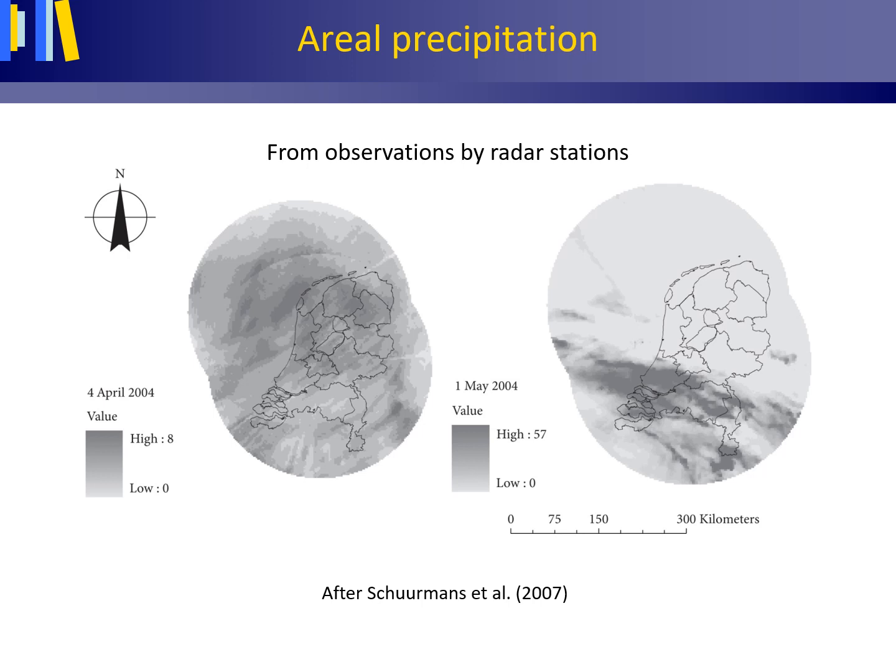Nowadays, good use is made of radar in estimating aerial precipitation depths. Radar does not directly measure precipitation. Radar is an acronym for radio detection and ranging. With radar, an empirical relation between the radar reflectivity and rainfall is used. More reflectivity indicates a larger likelihood of precipitation.